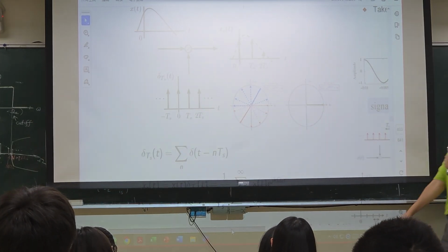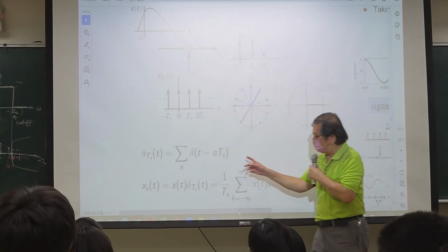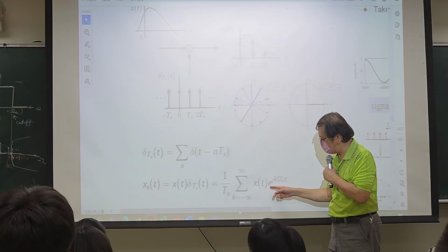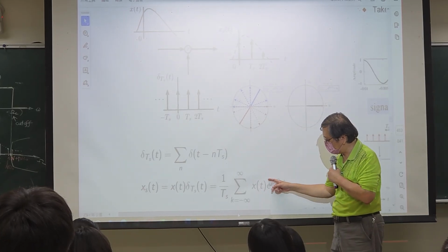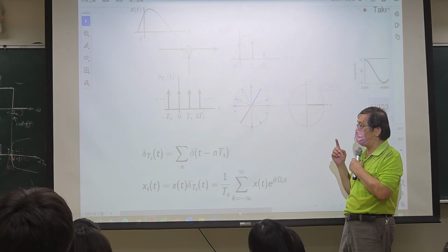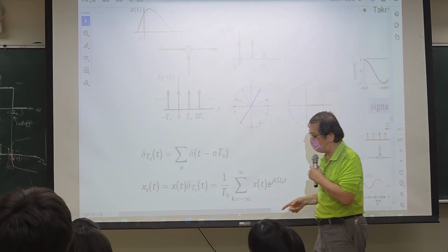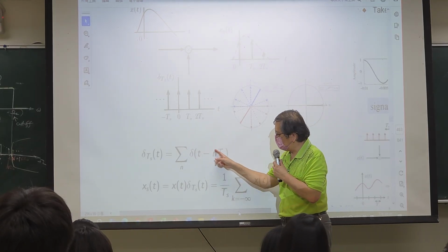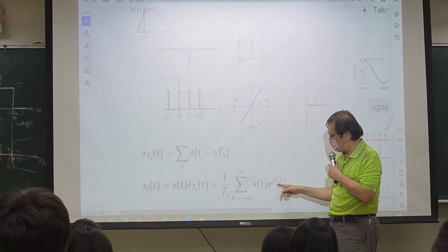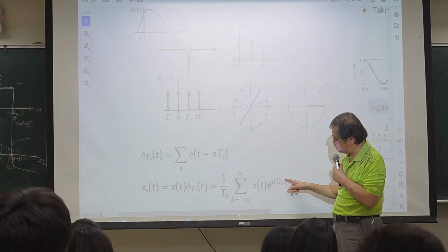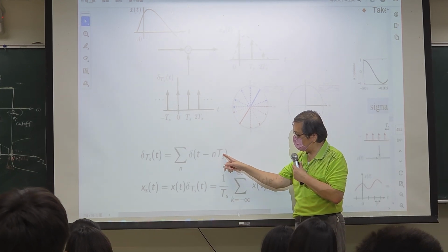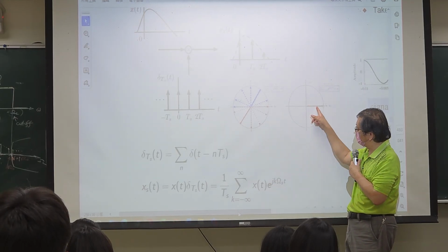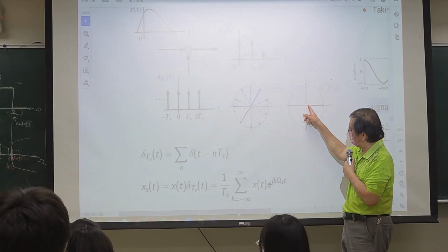Oh, by the way, there's a very interesting figure. This impulse train can be expressed as the summation of those complex exponential functions. And if you look at this a little bit deeper, you will see a very interesting result. Now, when the time t equals n times Ts, when t equals a multiple of the sampling time, then each term is equal to 1.